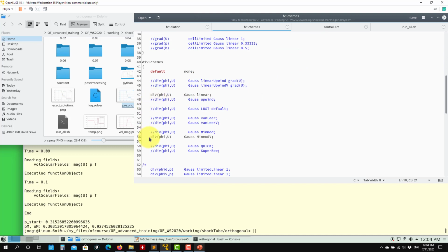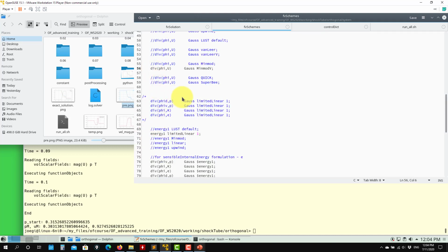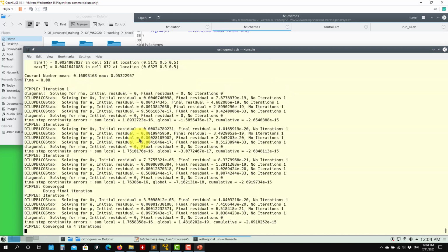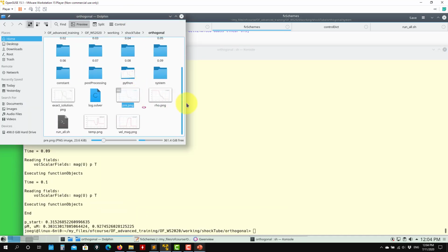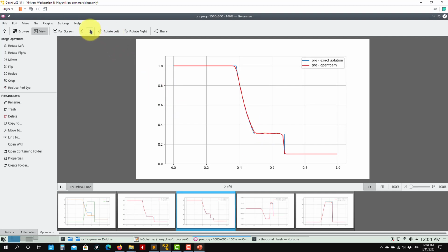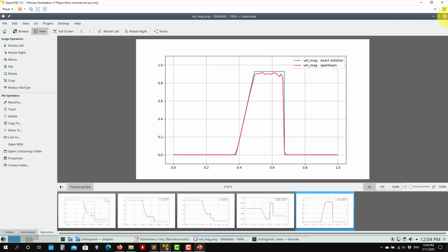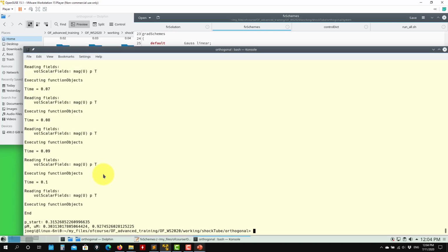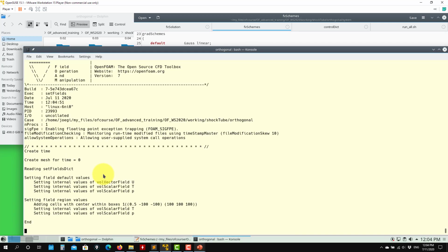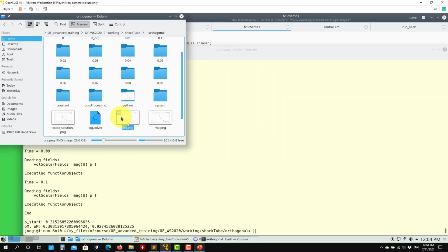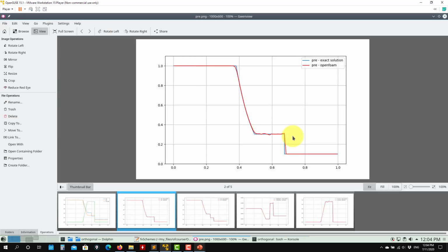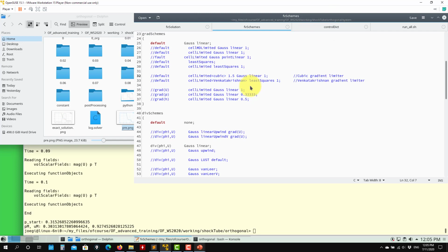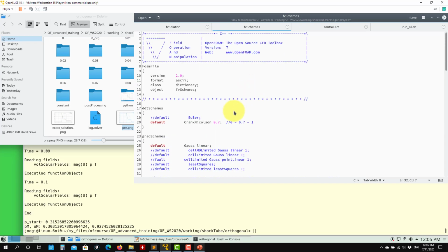So if I go now instead of, oh, well, it was working with MinMod. Okay, so let me go here now, fully linear here. Now see the behavior there. So the linear is oscillatory. Let me go here and put this one. Okay, put it here, run. It was quite fast. Let's see what happened now. See here you have the oscillation. Okay. Previously, I was using the MinMod. So you saw here also the problem with the Crank-Nicolson.